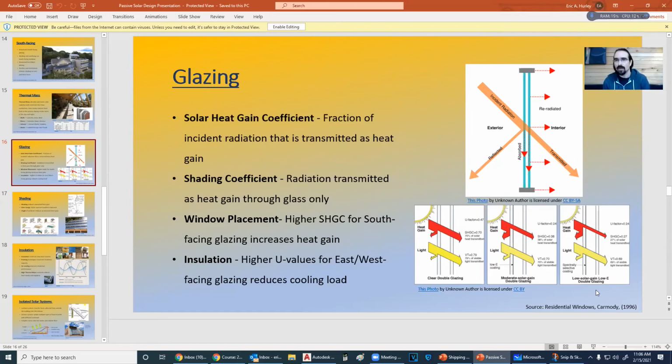If you want to use a low E window, then it can be used in an indirect system. You can use a non-low E window if you want a window that allows all of the UV gain possible. Use that on an exterior greenhouse system, or on an exterior indirect solar capture system where you're heating up another thermal mass and then transferring that energy inside. And then you're not losing any of that extra heat gain that you could be getting, but you're also not bringing unwanted heat gain into the house or losing a lot of your heat because of a higher conductivity through the window assembly. Right, right.